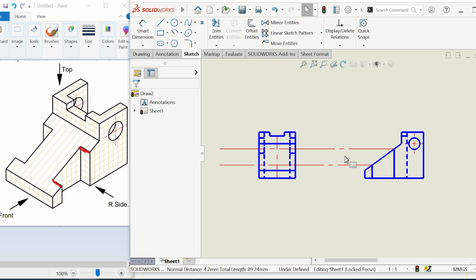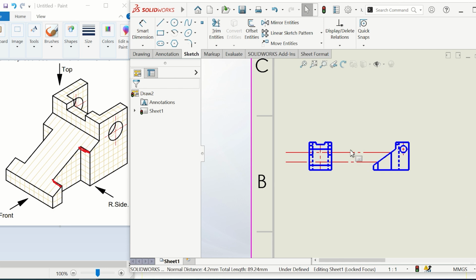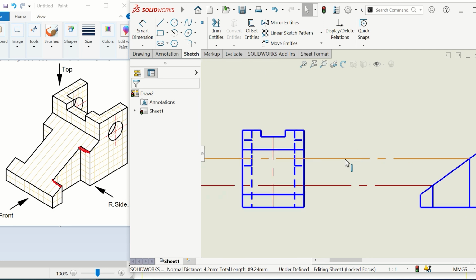They were still physical lines inside of SolidWorks. Okay, I'm designating them to be placed in the construction entities layer, but they do not become construction, meaning that these are still real corners, real edges that can be later extruded or made into three-dimensional shapes.